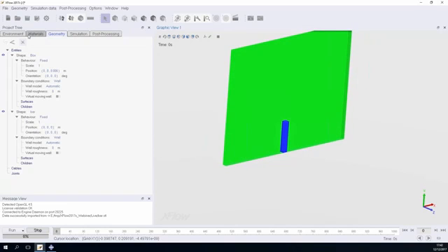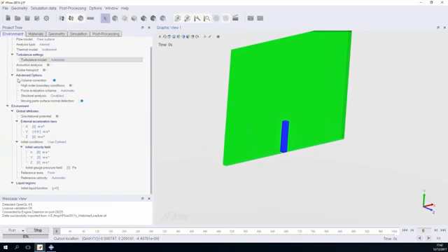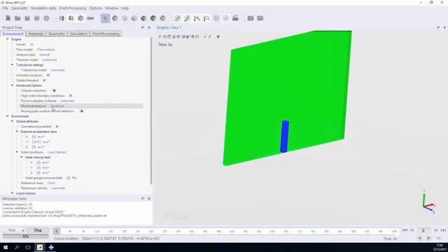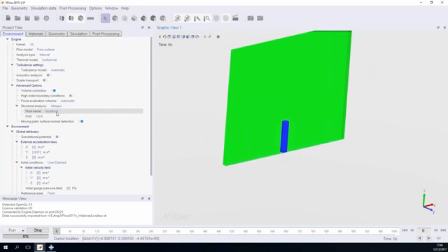So far so good. Now that's where the new thing comes in. If you go back to environment in XFlow, now we have a structure analysis option, which is again available for labs or expert mode, and we can select Abaqus. And now we can select the host name where the Cosimulation engine is going to be running, and the port that it's going to use. By default it is 2024, but you can select any port that you can use for Cosimulation.